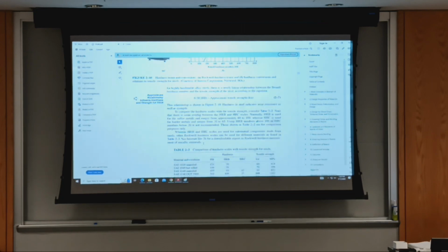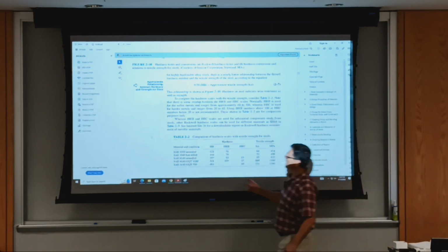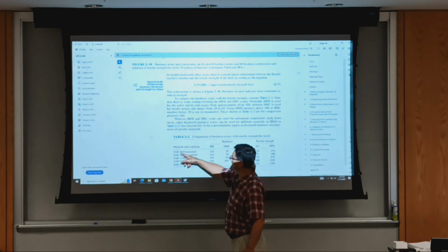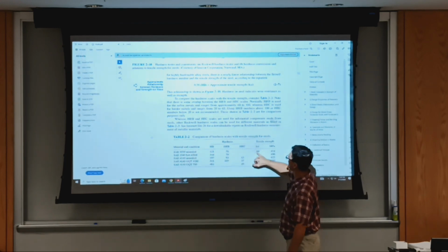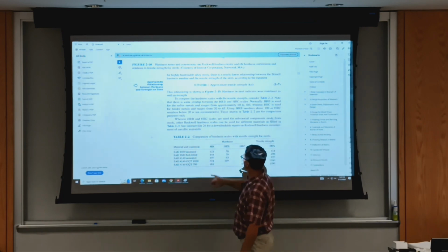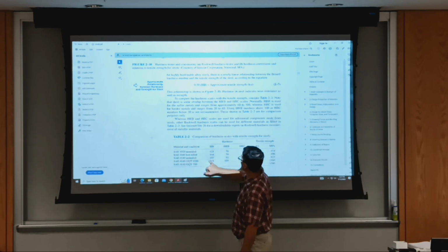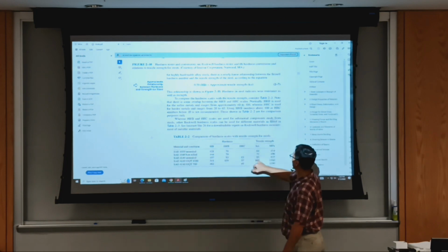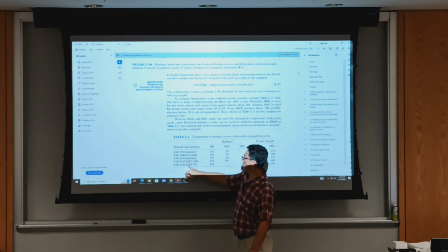Anyway, so this is to get an idea of the hardness numbers you'd expect based on the conditions. So low carbon steel annealed, tensile strength, soft, and then quenched and tempered. Brinell hardness went more than double. Rockwell B, Rockwell C, and the tensile strength. All right, so all quench and temper.